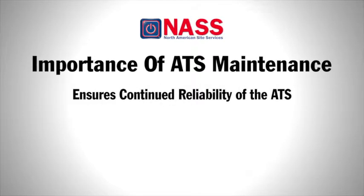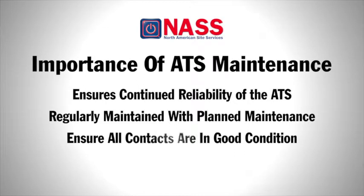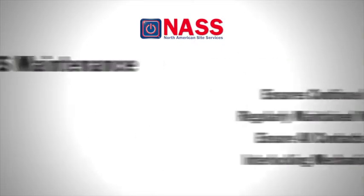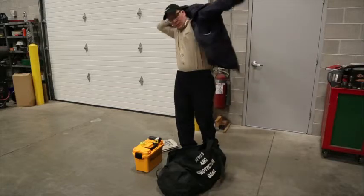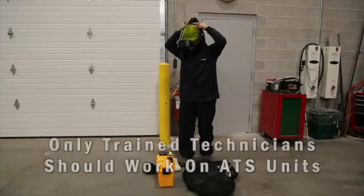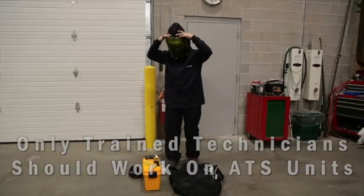The ATS is a very important component within a standby system. To ensure continued reliability, the ATS unit should be regularly maintained as part of a planned maintenance program. It is crucial to ensure all contacts are maintained in a good condition and their interlocking mechanisms are in full working order. Planned maintenance of an ATS unit must be carried out only by experienced and qualified service technicians.